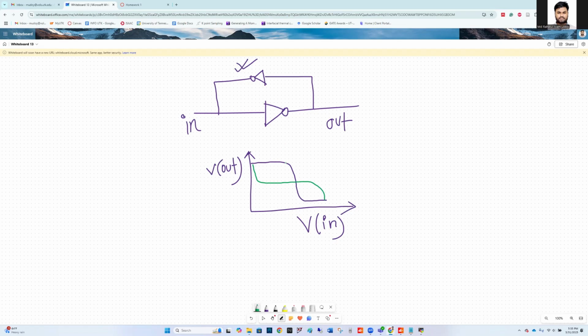So how can we do that? In HSPICE code, you do not need to run two inverters, or plot input and output characteristics separately. Instead, you can just simulate one inverter, take the data of input node voltage and output node voltage, and then just plot it. You can extract the data from HSPICE and plot it in MATLAB. So I will use that way. I will extract the HSPICE results file data and use those data to plot in MATLAB.